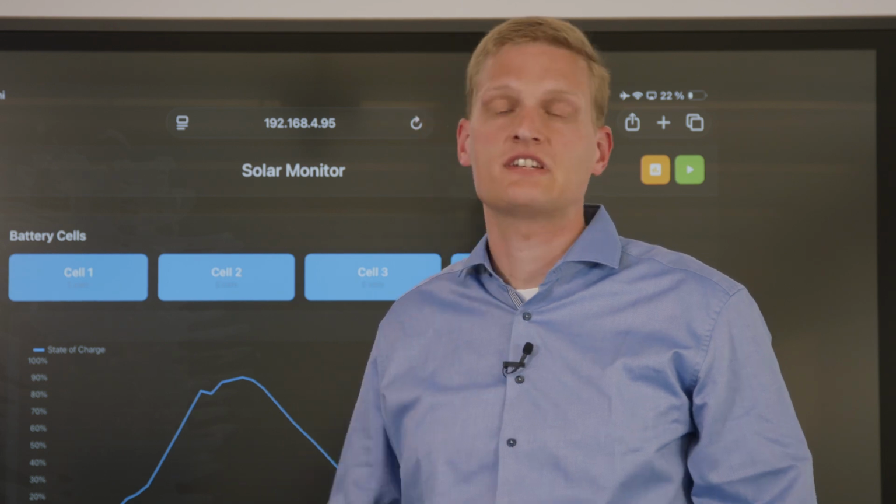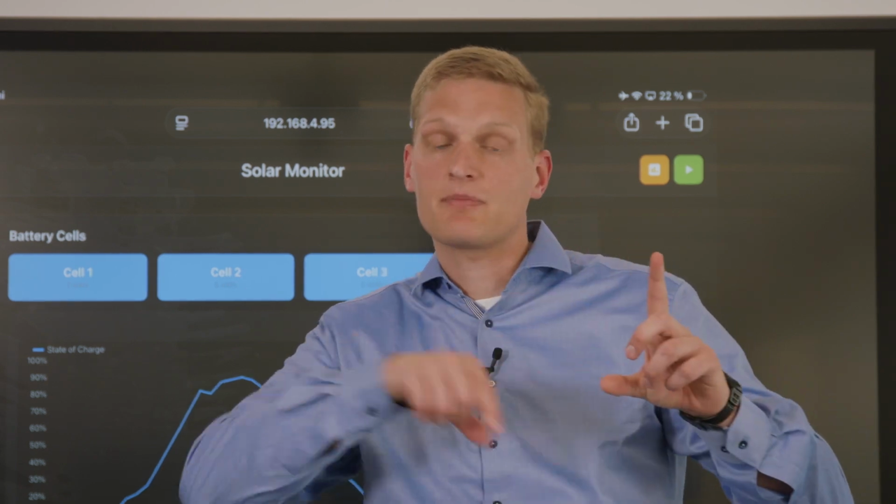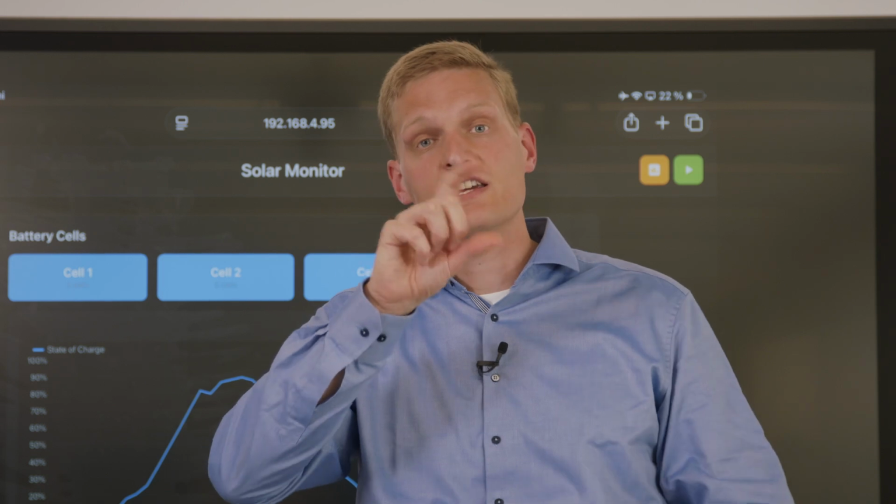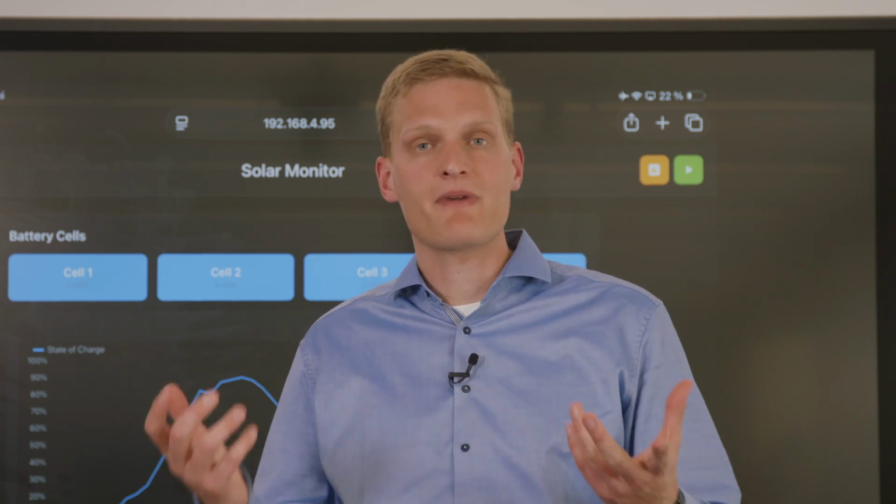So to optimize, we said that a PV panel costs around 10,000 South African rand, 500 euros, and a battery costs 1,500 euros, around 30,000 South African rand. So that your learners can make up a table, say 1 PV panel, 1 battery, 2, 2, 3, 3, 4, 4, so that you have a matrix and you can put in there till what time your energy stored in the batteries lasted and how much it cost, because the maximum, 100 PV panels on the roof, 1,000 batteries in the basement, yes, it works, but it's not sufficient. You have more than you need and you pay more, and you could have the same result for less money.